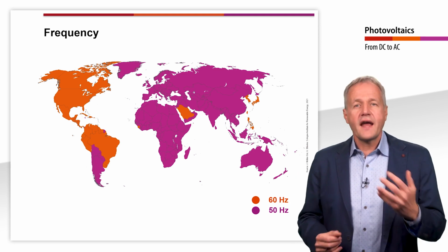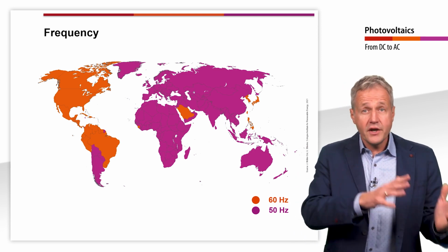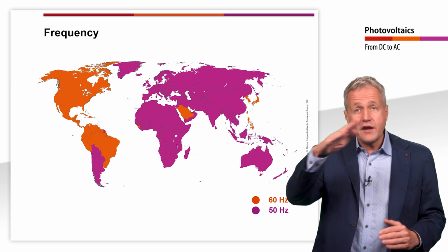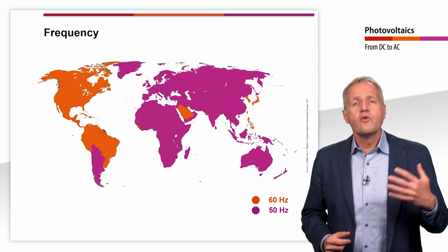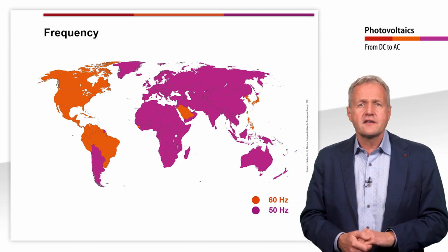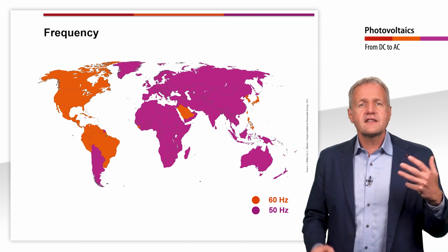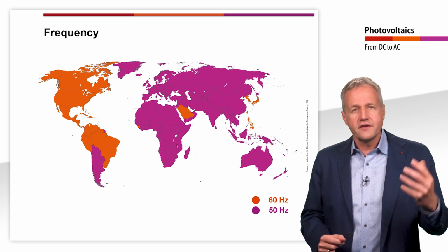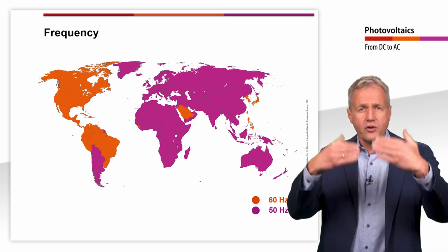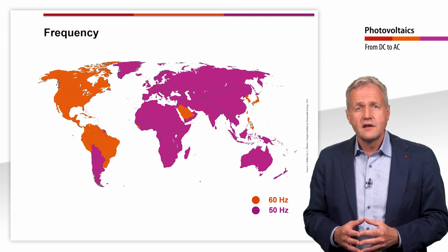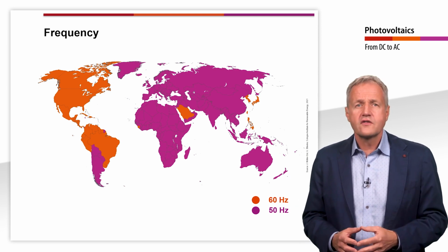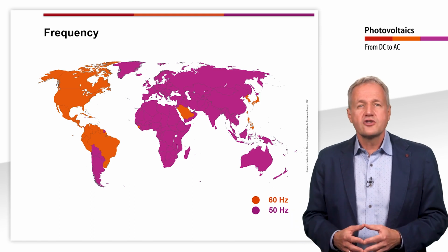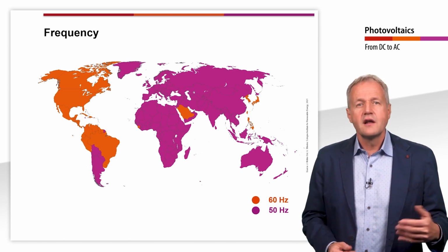But to connect the inverter to the public grid, we need a sine wave alternating current. A square wave current would generate numerous harmonics. Hence the grid gets polluted with so-called noise, waves with a multiple of the sine wave's frequency. These harmonics could damage the connected loads. We will deal with the topic of harmonics in more detail later.